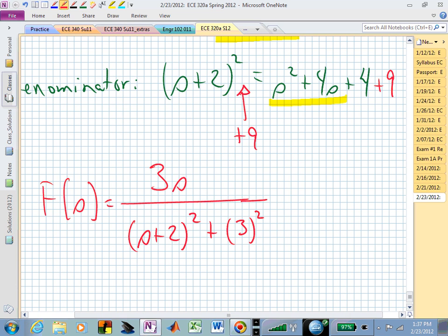Left half, they're going to have negative parts, aren't they? They're going to be at minus 2. They're going to be on this vertical line that's 2 into the left half plane. It's 2 away from the imaginary axis, and they will be located off of the real axis a distance of 3. So we're now at minus 2 plus and minus j3. Those poles are immediately obvious from the way that denominator has been factored. Those are right at minus 2 plus and minus j3. Boom. What does that tell us?